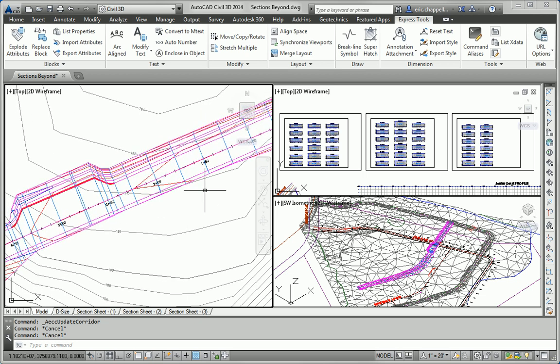Using the Section Editor, we removed the ditch from that part of the corridor. So we went in and changed a few settings at a few stations to make a small change. Now if we wanted to remove the ditch from hundreds and hundreds of feet along the left side of the corridor, we would have to handle that possibly a different way.